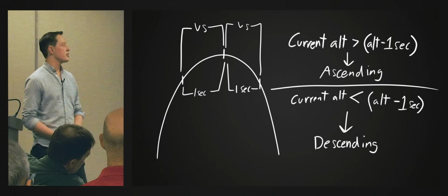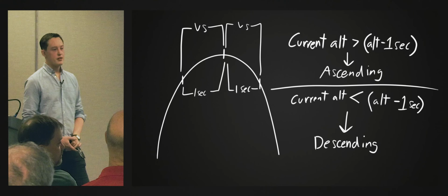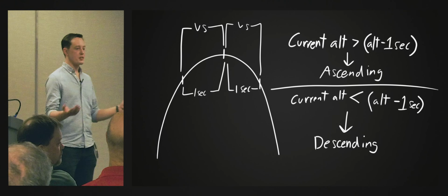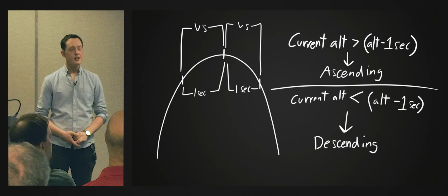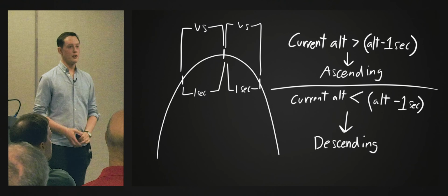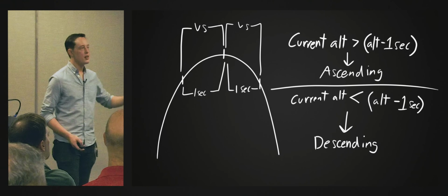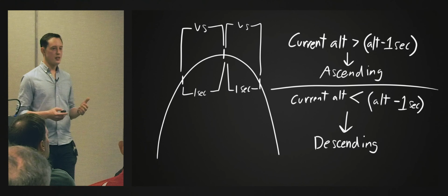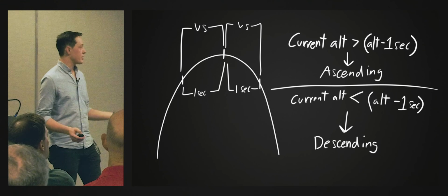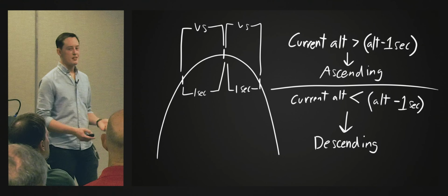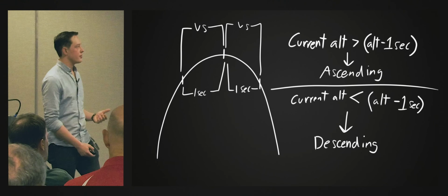You can use velocity and acceleration too, but especially as your flight profile gets larger, it's difficult to rely on that. I don't know what scale of rockets you fly, but if you use acceleration, especially with MEMS quality sensors, sometimes it can be hard to figure out exactly where apogee is. So I think this is a more robust approach. And since detecting apogee in software like this isn't extremely time sensitive, I like this approach. But again, I don't know if I've emphasized this enough, but there are no right answers here, right? This is just a suggestion for how you can do it.